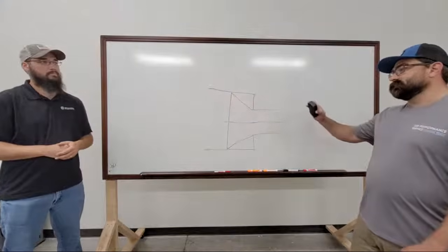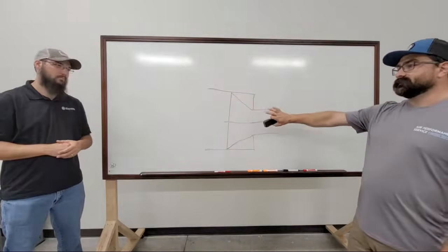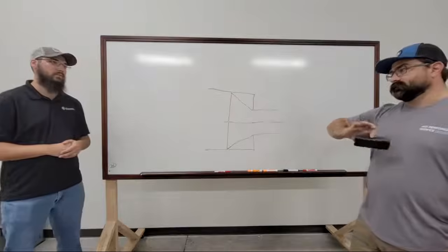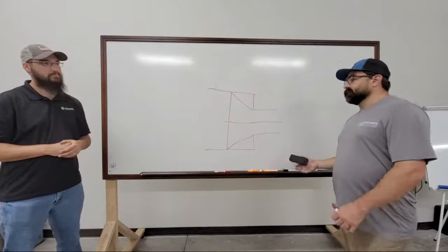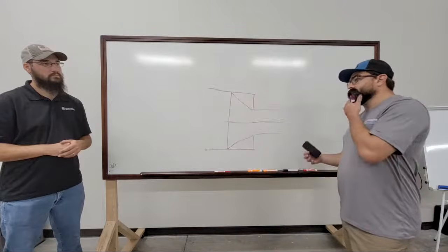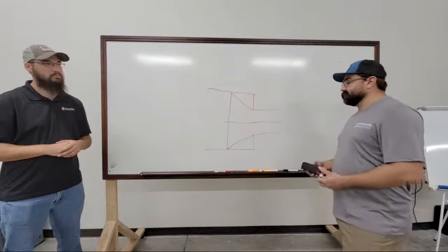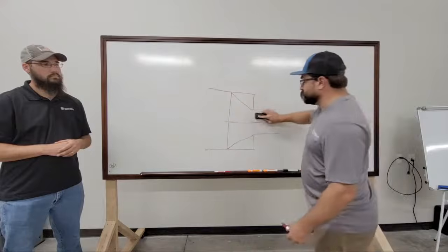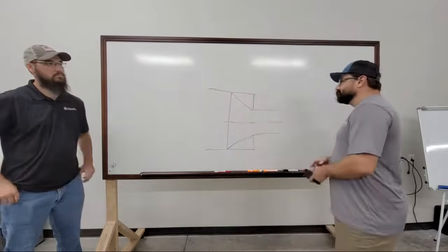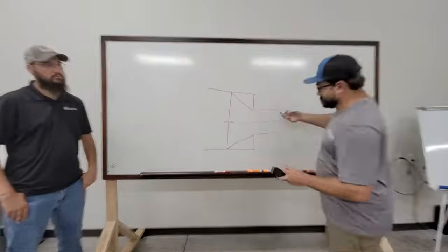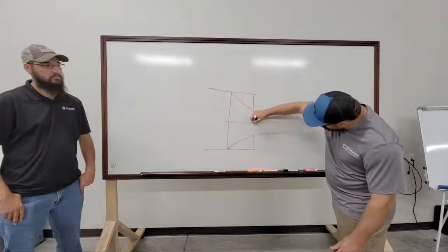But you can actually control flow in this instance. Whereas a true Texas multi-zone is constant volume, you're not controlling flow. So these do have metering, these do control flow in the right circumstances. If the box is set up to control flow, it can control flow. Whereas a true Texas multi-zone does not control flow at all.